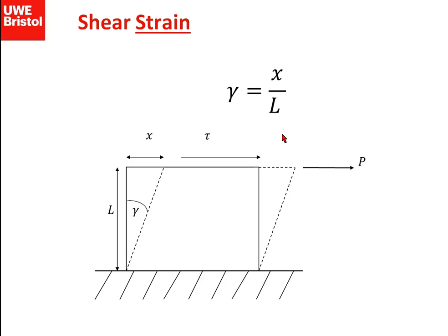Okay, so shear strain. Notice there's something interesting about shear strain, which is that if you were working in radians, your shear strain and your angle, if we consider this to be an actual angle, are the same values. This only works for radians, by the way. You could try it in your calculator.